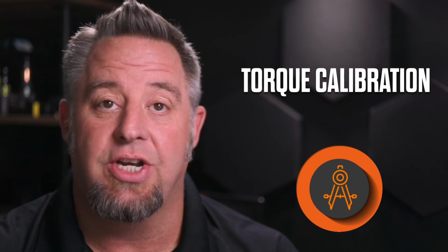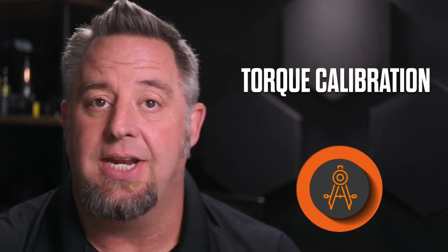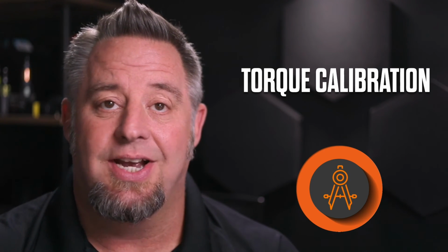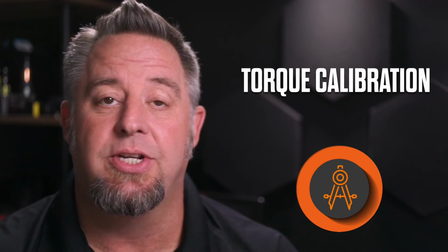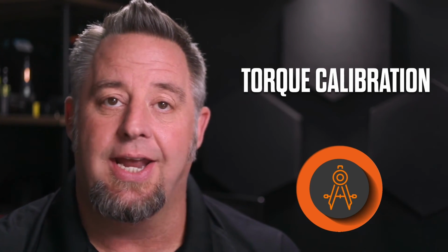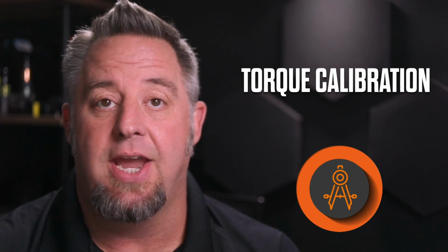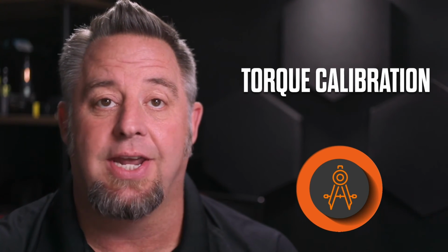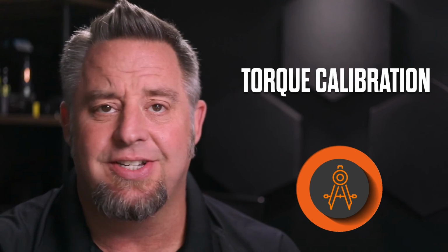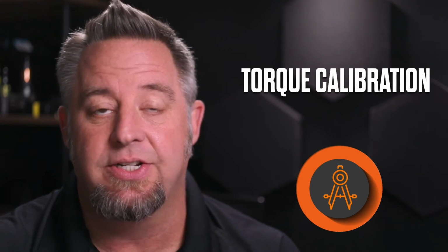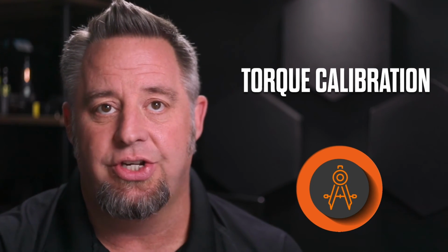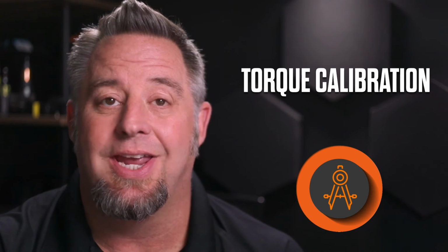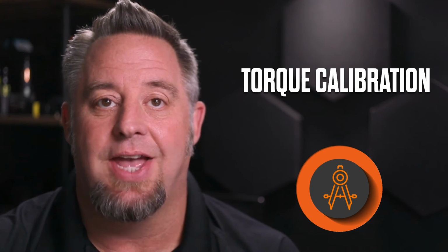We do have customers, however, that will be testing their tools on a certified and traceable calibrated analyzer. Every time they do a test on that particular tool, those results are traceable to that particular torque analyzer. They test their tools periodically, and as long as the tools are performing correctly, they will not send those tools in for calibration or recertification until they start showing signs of moving out of calibration. So there is a time-based type of calibration, and then there's a performance-based type of calibration. Depending on what your organization feels comfortable doing, there are definitely advantages to moving to a performance-based type of calibration. There just is a lot of testing that needs to be done for that as well.